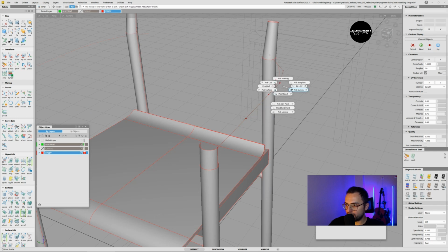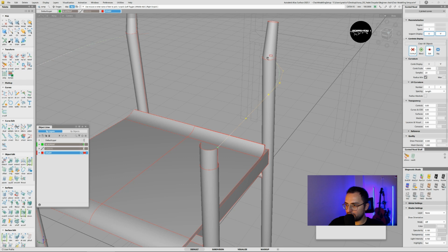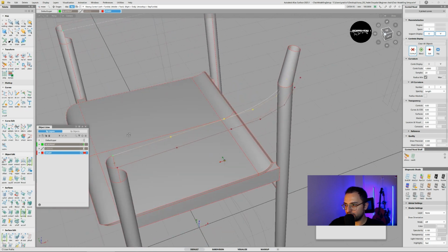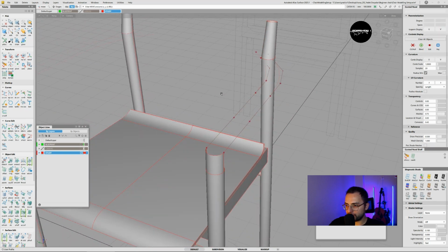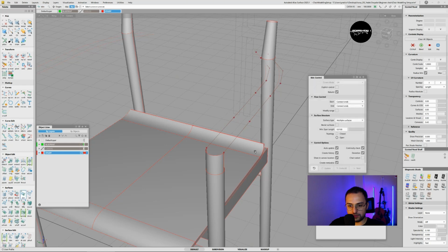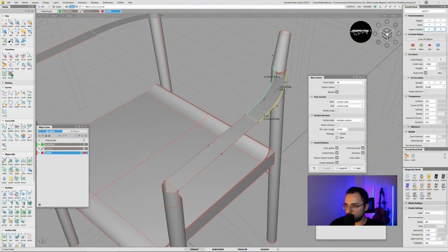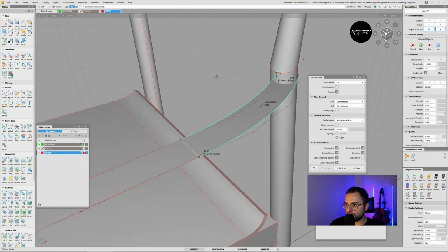Now we can pick these curves, delete history, since we capture more or less the design intention over there. Set pivot here, copy and paste, move over there, and create skin between. I always find it hard to locate these two. Yeah, we don't need to continue.